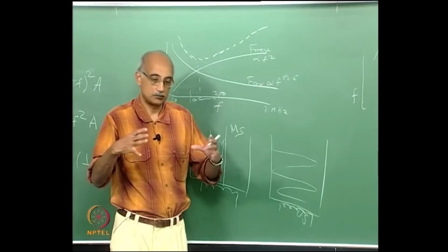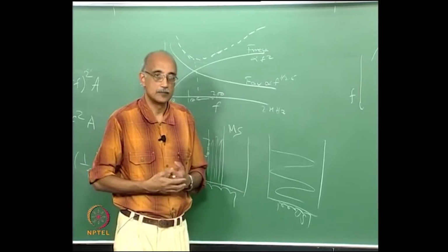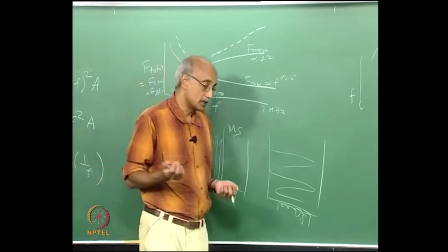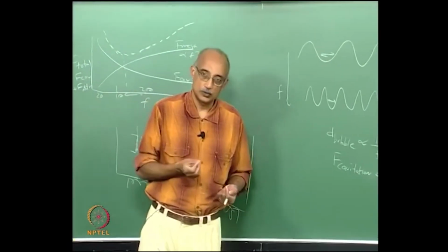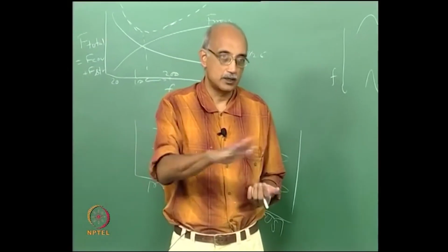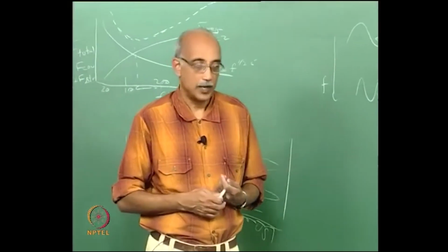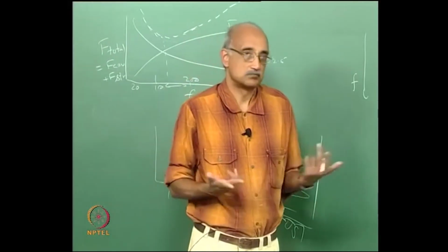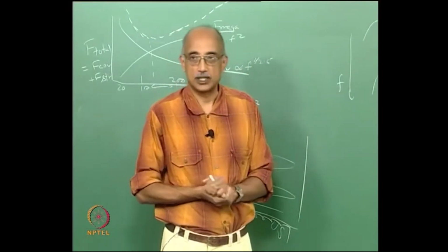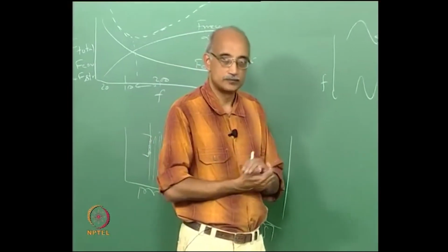at a time. You will have a tray or a basket with hundreds of parts in it and you have to clean all of them simultaneously. So, you really cannot do that very effectively with megasonic fields. So, even though megasonics are wonderful, they are really restricted in their use to cleaning fairly simple and planar substrates. For example, a surface like this would be nice to clean using ultrasonics, but if I am trying to clean something like that keyboard, very hard to do it with megasonics because it is not a line of sight cleanable object. There are a lot of hidden areas, features, recesses that a megasonic field just cannot reach.